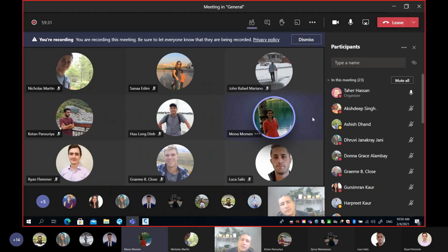When I do that, it brings fillet. So you have to be within the selection. F in general, outside any command, if you type in F while you are not doing anything, it means fillet, like fillet radius. So you make a radius between two lines. But if you type in F while you are within the command, when you delete the lines, then it will take you into the fence selection.